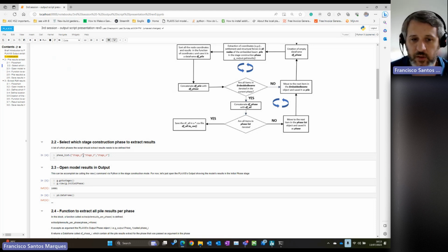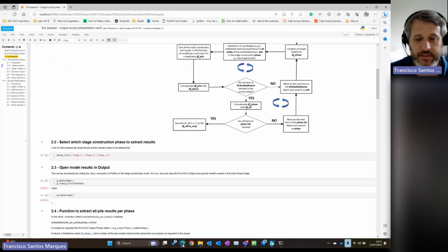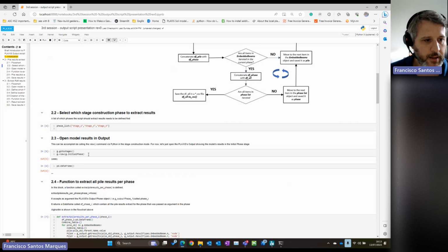What I'm defining is strings, because if you recall last time, we called these stage_2, stage_3, and stage_4. There will be a getattr later that will try to make an association based on this string. It will find the associated Plaxis global object that is associated to the phase, which we will see later. Okay, and let me just initialize this.